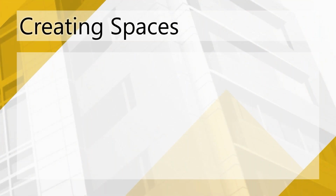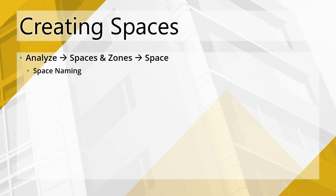So when we're talking about creating spaces in the Revit environment, where we typically will go is the Analyze tab within Revit, the Spaces and Zones grouping, and using the Space command. And we're going to be using that today live. Also, as a part of this, there's a follow-up piece that actually leverages space naming from that same Spaces and Zones, and we'll be doing that in a future step.